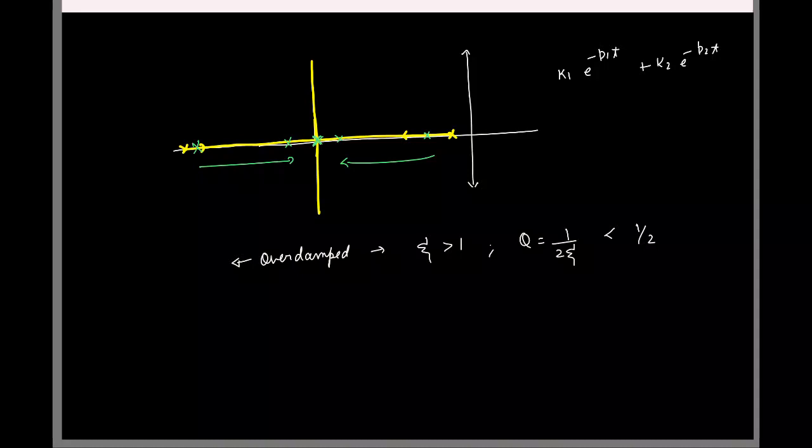So your settling response will be dominated by the low frequency pole. Now you want the system to respond very fast, right? So for the dominant pole in the closed loop system, do you want it at a low frequency or at a high frequency? You want it at a high frequency so that the lowest frequency in your closed loop system is high enough that the response decays quickly.